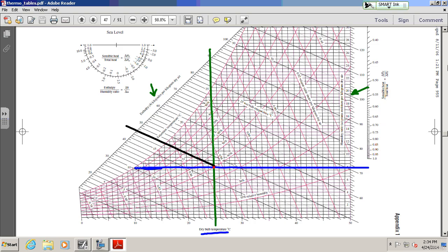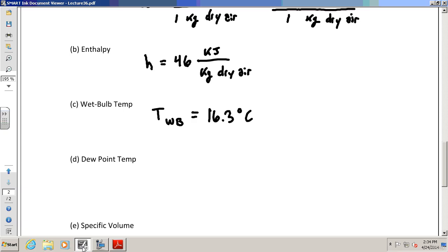What do you think? About 10? Yeah. I think it's about 10, right? It looks pretty close. I guess, again, somebody could probably argue that it's a little bit bigger than 10, a little bit less than 11. It's somewhere between 10 and 11, but, you know, how close can you get? So we'll say it's 10, okay? So the dew point temperature, TDP, the chart gave us was about 10 degrees Celsius.